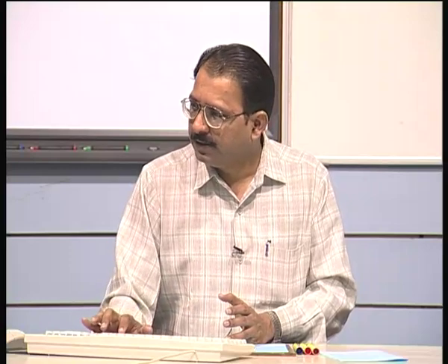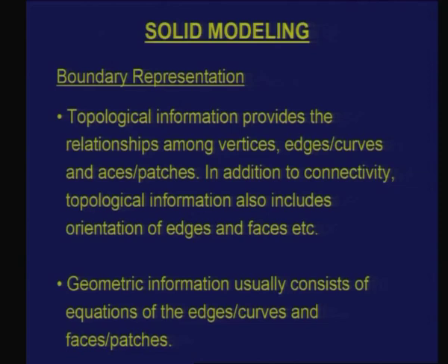Like, basically the topology of a solid consists of the relationships in terms of vertices, edges, curves, faces and patches. Okay. So how one particular face or patch is related with another patch, whether it shares a common edge or common curve, is a part of this. And this complete connectivity information is stored separately apart from the geometric information.